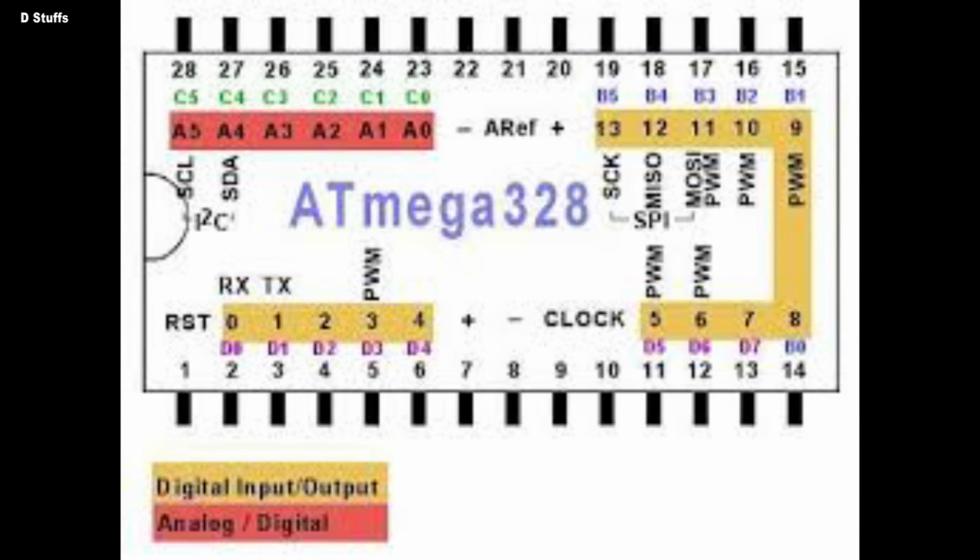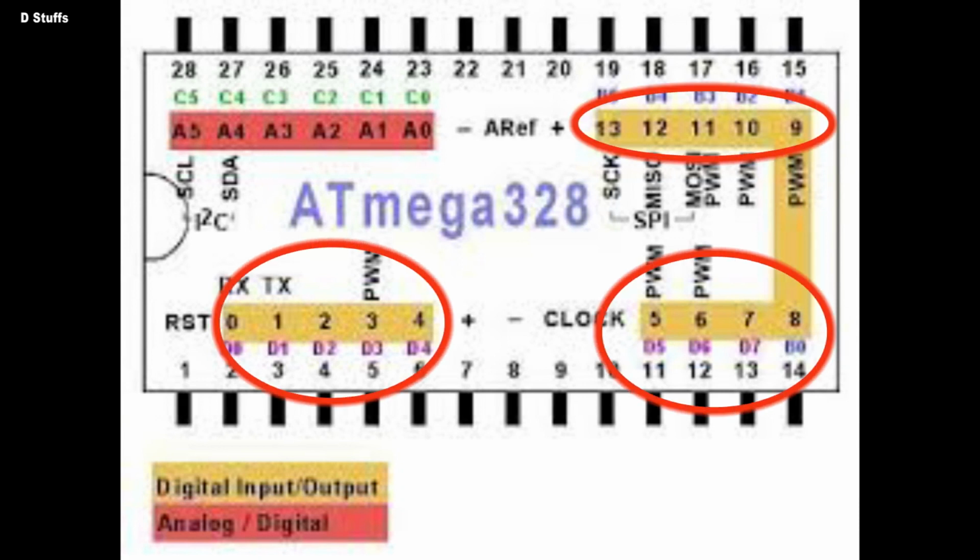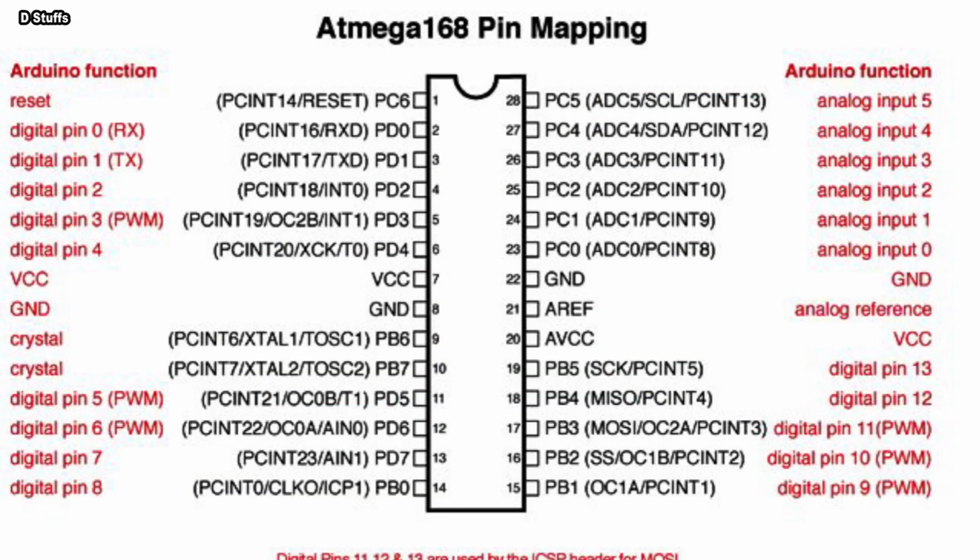To expand the understanding, you are free to use any of the digital pins to connect a TTL level or transistor logic level, that is 0 or 5 volts. If you want to connect the LED to pin 2, you are free to do that. What about pin 3?